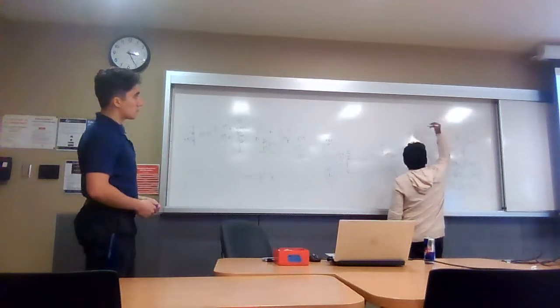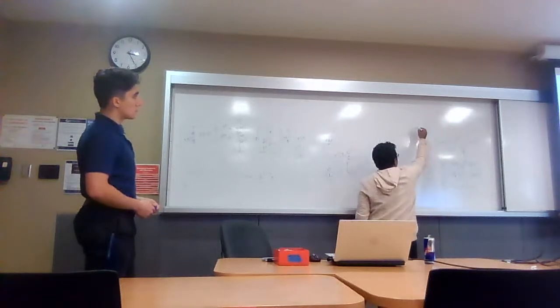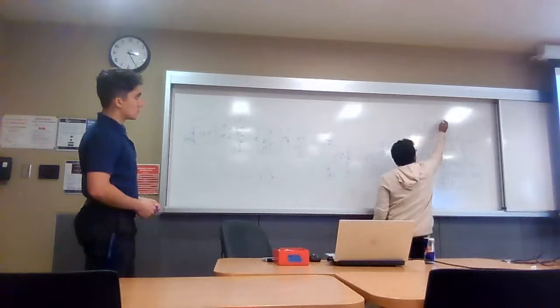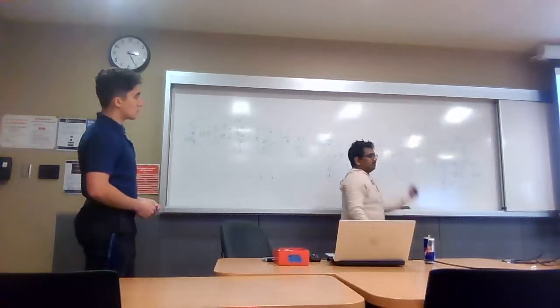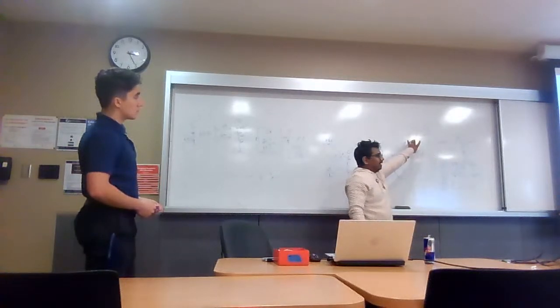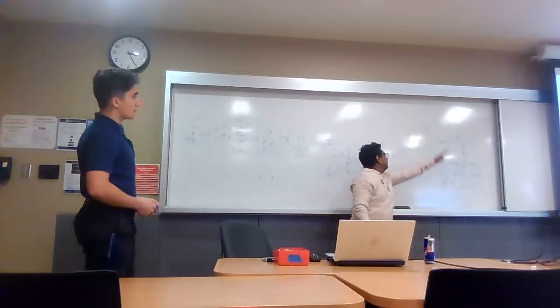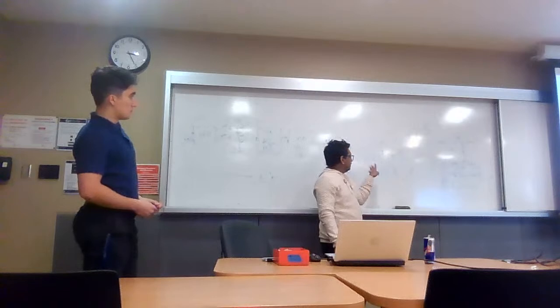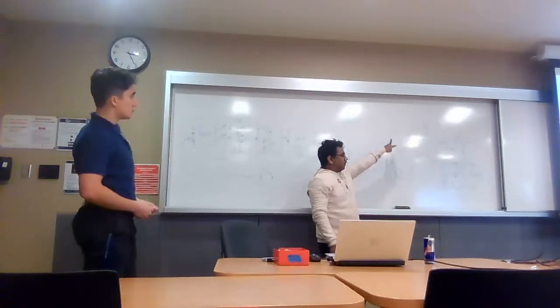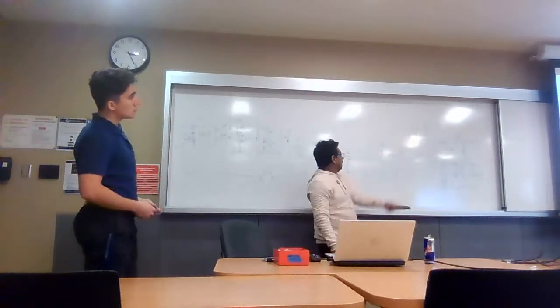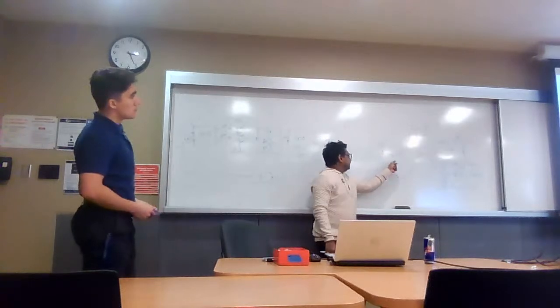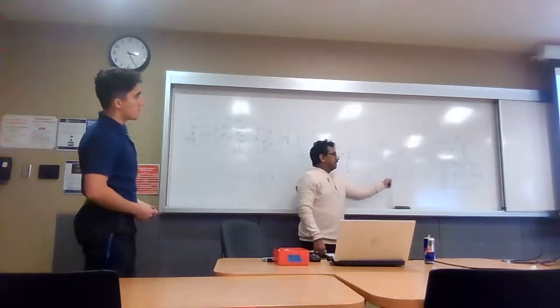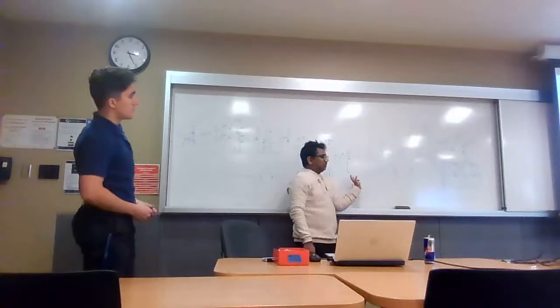The same structure, and just this output is connected here. This structure will also work like an oscillator. However, in industry, they prefer this inverter as an oscillator because its performance is really good compared to common source-based oscillation. However, here we can see it generating a fixed oscillation.